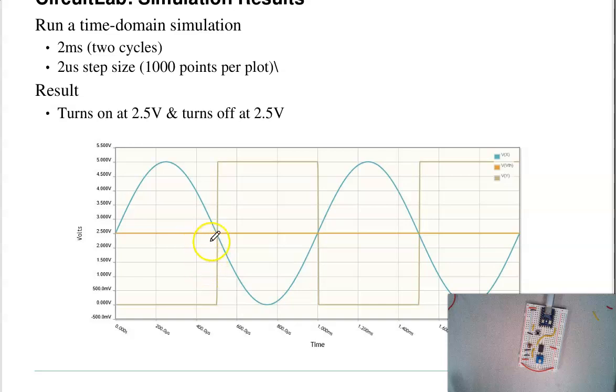So this is the on voltage. When it goes below, that's off. When it goes above, it turns off. Goes below, it turns on. The reason it does that is it's connected to the minus input. And notice V on equals V off. That's a comparator. If I add noise to the signal, I get chatter.